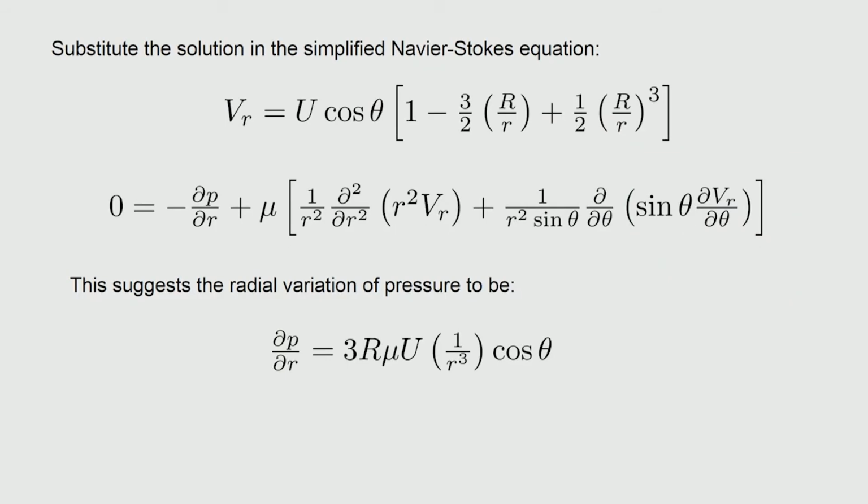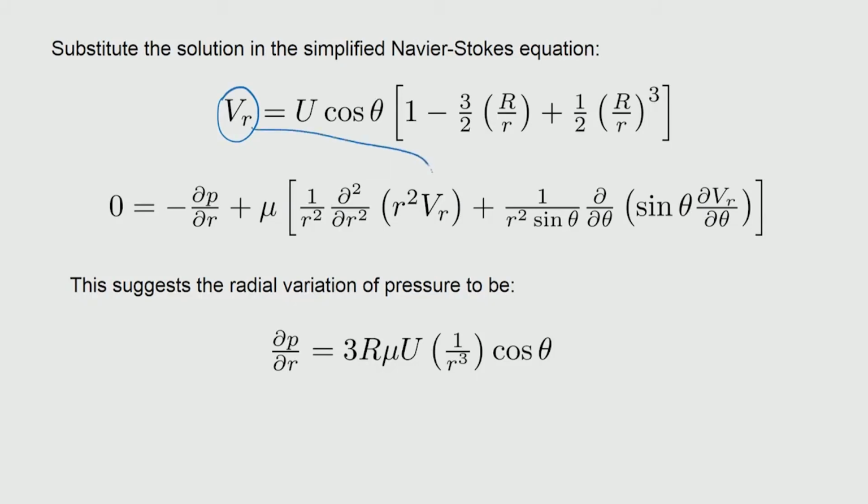Okay. So, for that what we need to do is go one step back and look at the Navier-Stokes equation, substitute the velocities and get the pressure distributions. If you have noticed in the previous session, we have already done that to see how the pressure variation will come once we have the velocity components available. So, we are going to do that here also. So, the velocity components are available. So, then we substitute that into the Navier-Stokes equation, but keeping the pressure variations intact, so that we can get some functional form for P.